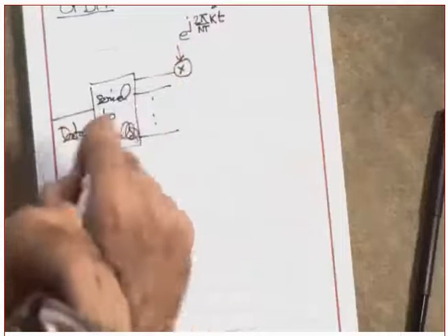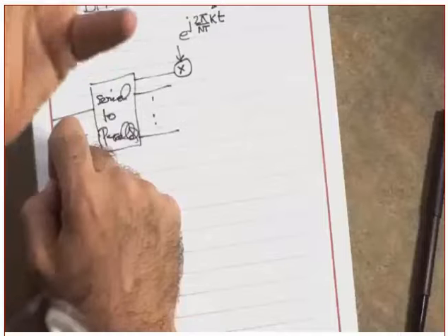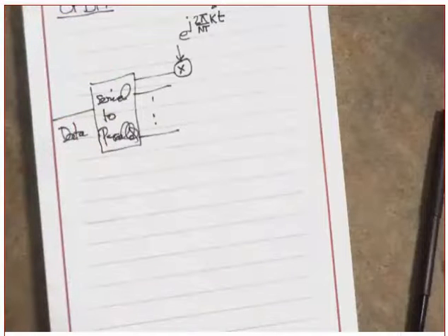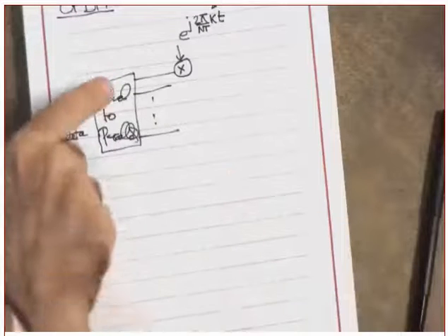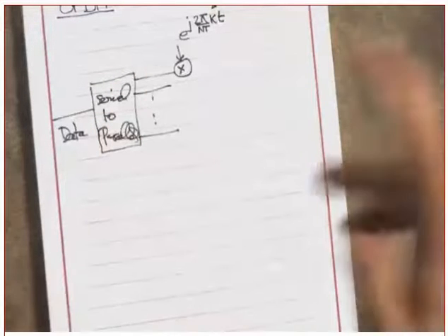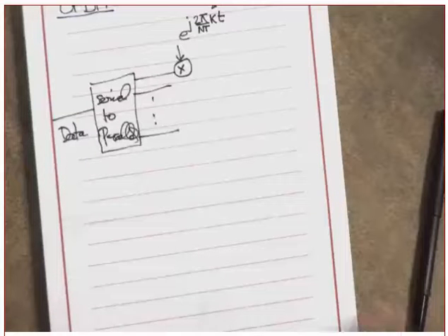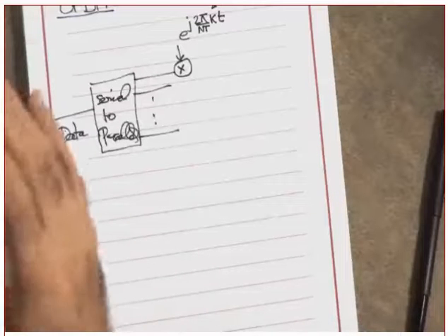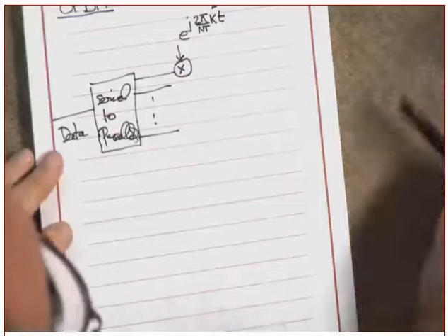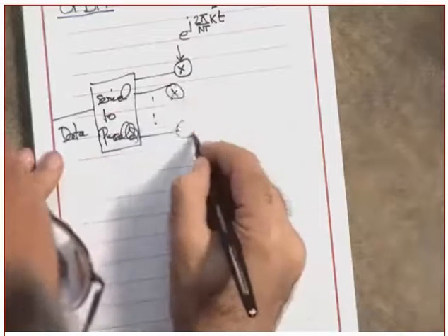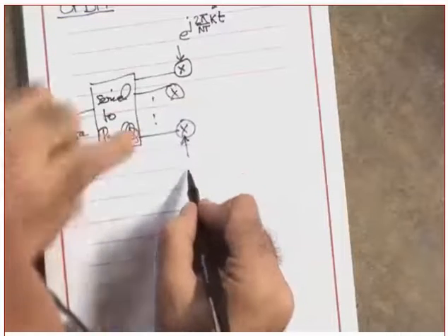Do you understand what this means? When I multiply by e to the j, it means sine and cosine. Did you understand that or not? In other words, one data stream is going to modulate a cosine. The other data stream is going to modulate a sine, but at the same frequency. Clear? Same thing with this one, but a different frequency.